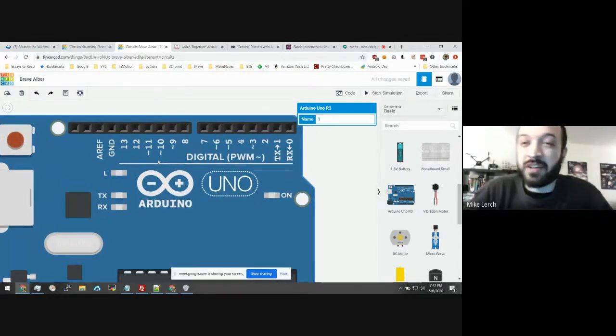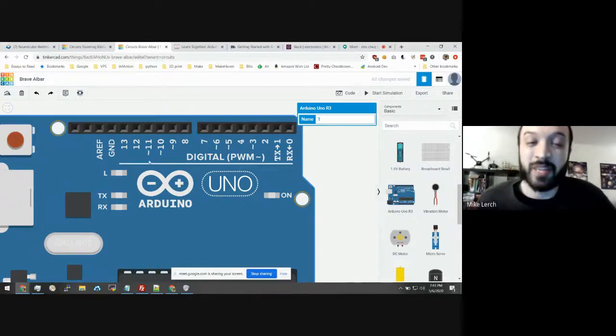So you could have, when I say listen, I mean like let's say a variable resistor, a pot. And if you dial that pot left and right, you can change that dial certain positions. The Arduino can listen on that input and tell what position that variable resistor is at, because you can label that pin as input.